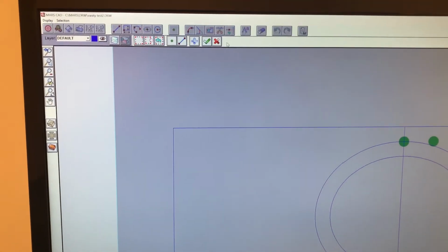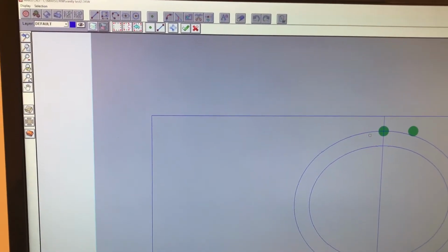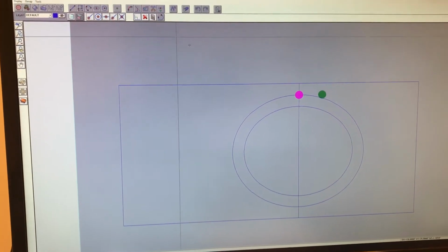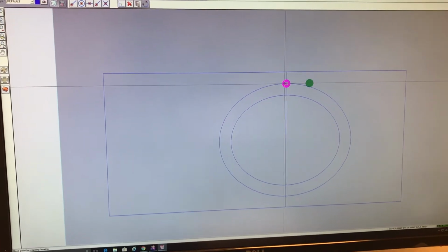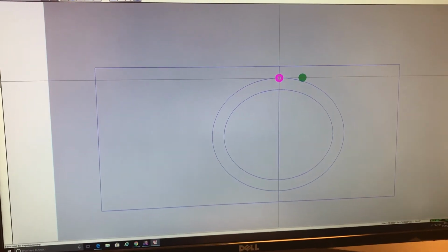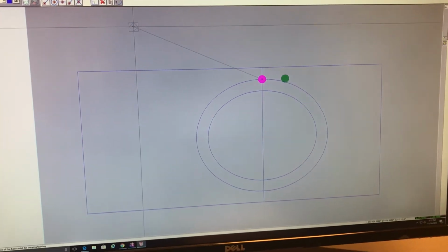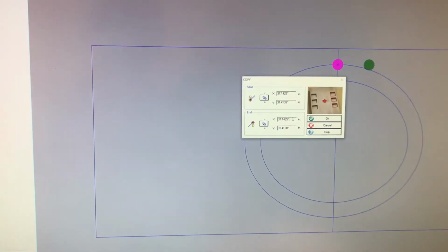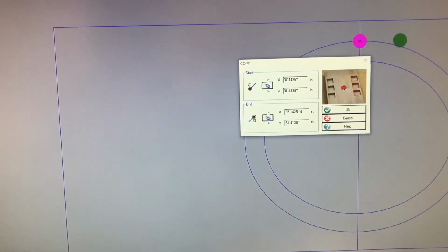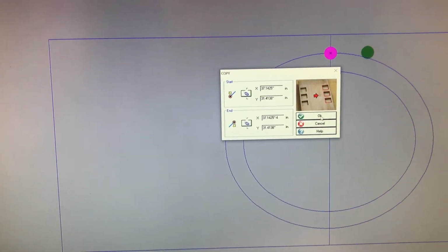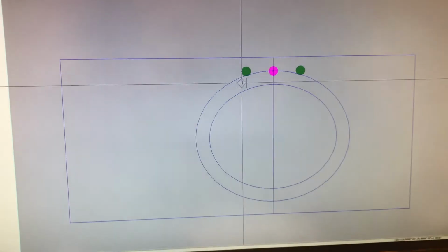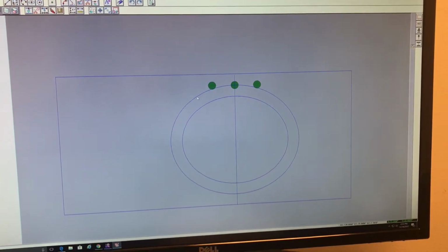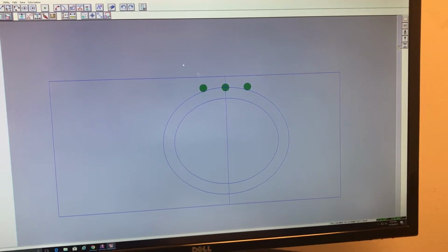Exit. I'm going to do it again. Copy. Select our hole. Green check mark to confirm. Select our precision start point, which is going to be the middle of the hole. Go to our little calculator. This time we're going to do a -4. Say OK. And now we have the hole on the other side for a total of an 8-inch spread.